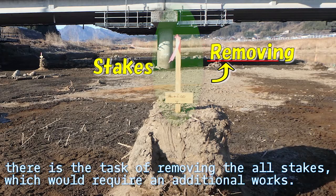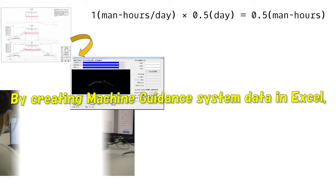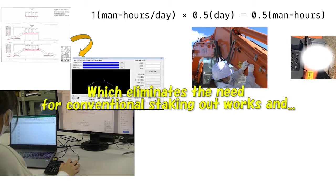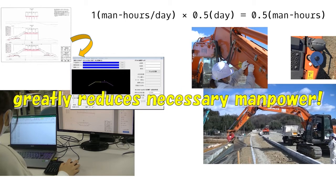In addition, after the completion inspection, there is the task of removing all the stakes, which would require additional work. With the introduction of this system, by creating machine guidance system data in Excel, we can see the current position in real time on the monitor, which eliminates the need for conventional staking out works and greatly reduces necessary manpower.